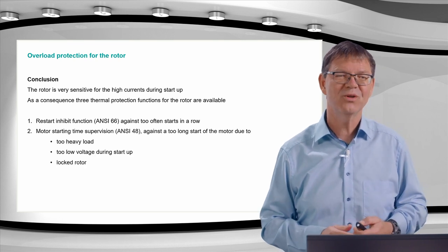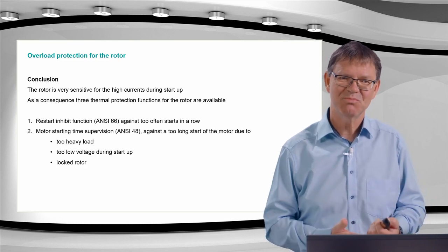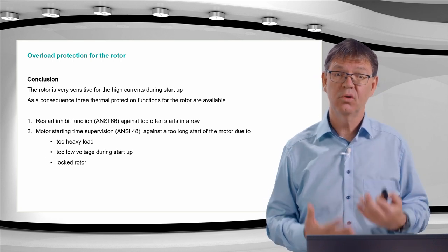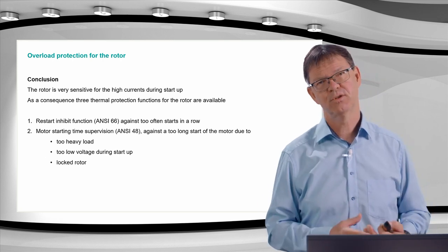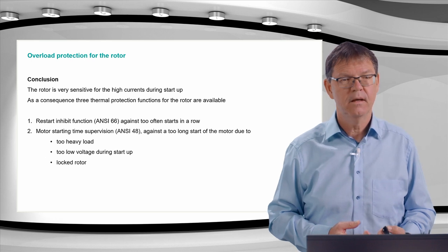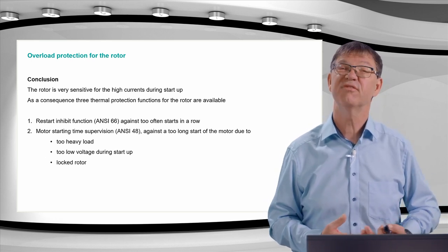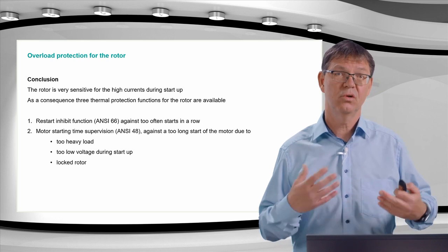The second one is the motor starting time supervision, ANSI 48, which protects against a too long start, so a single start which takes too long. This can happen due to a too heavy load, or if the voltage during startup is too low.